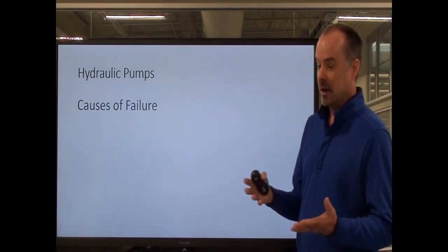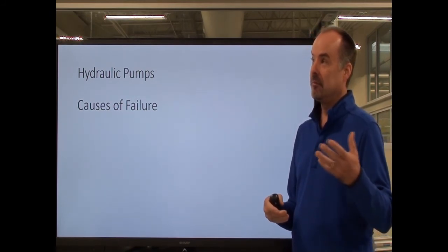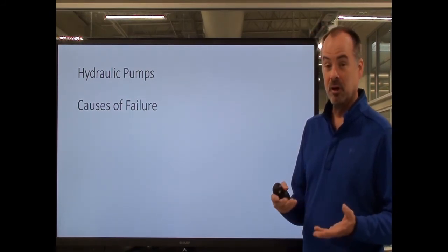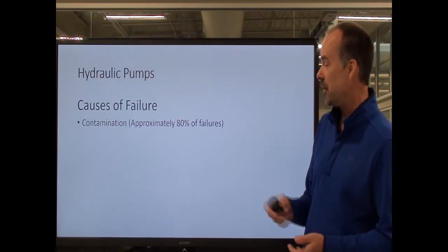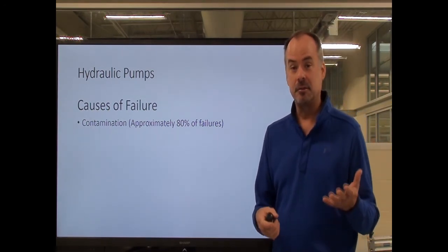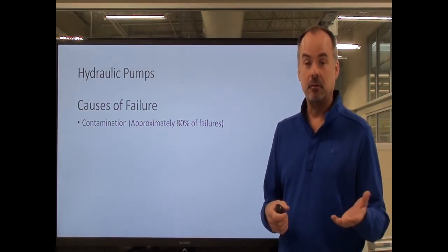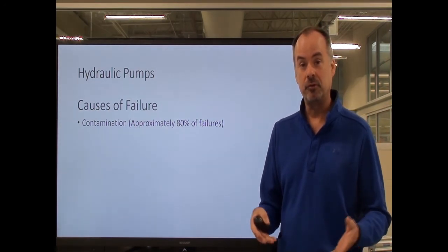So we've talked about hydraulic pumps and what they do, how they're constructed, and what can cause one to fail. 80% of the failures are caused by contamination. What I mean by contamination is you get dirt or other types of contaminants in your hydraulic reservoir, your tank.